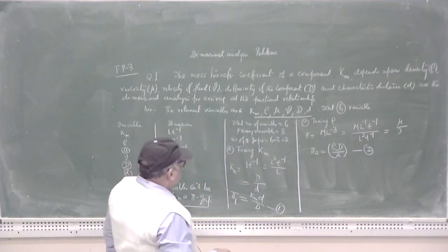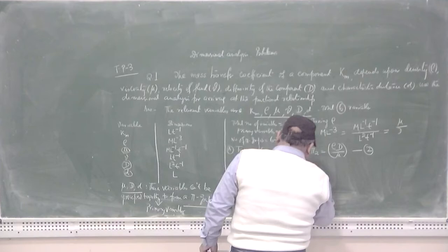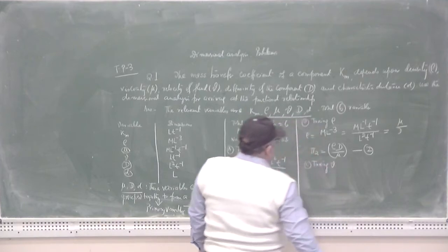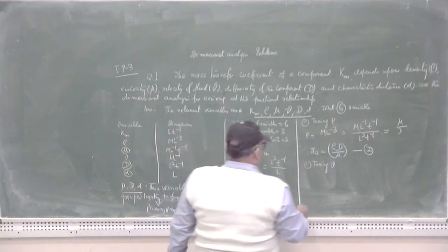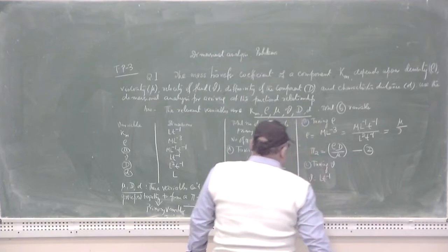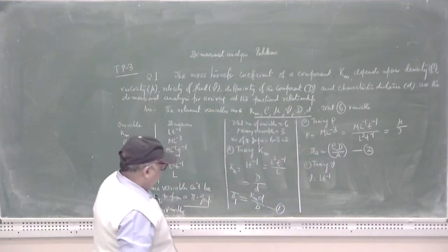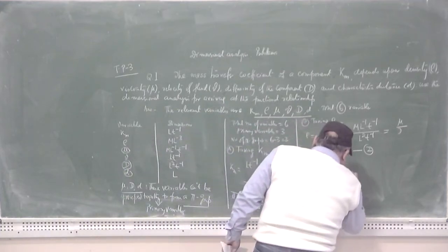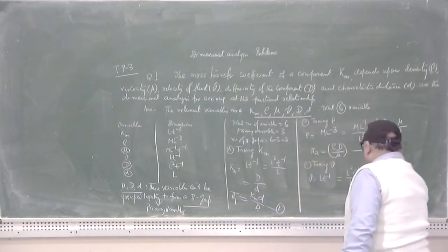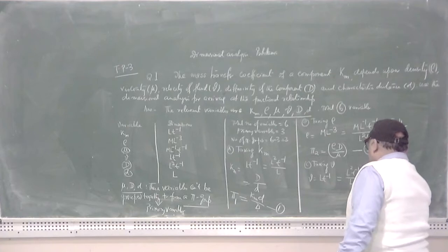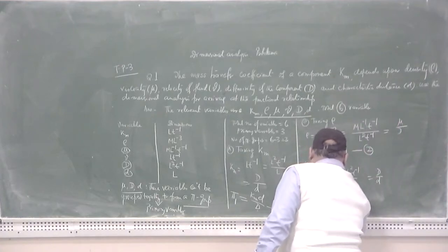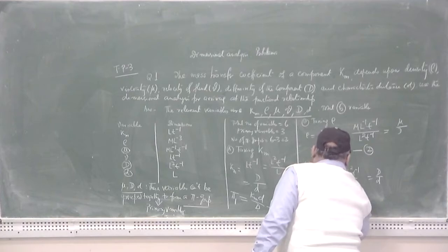Now taking the last one, that is the velocity, taking v, that is equal to L t to the power minus 1, that may be written as L square t to the power minus 1 divided by L. So L square t to the power minus 1 is equal to D divided by small d. So the third pi group associated is v d upon D.